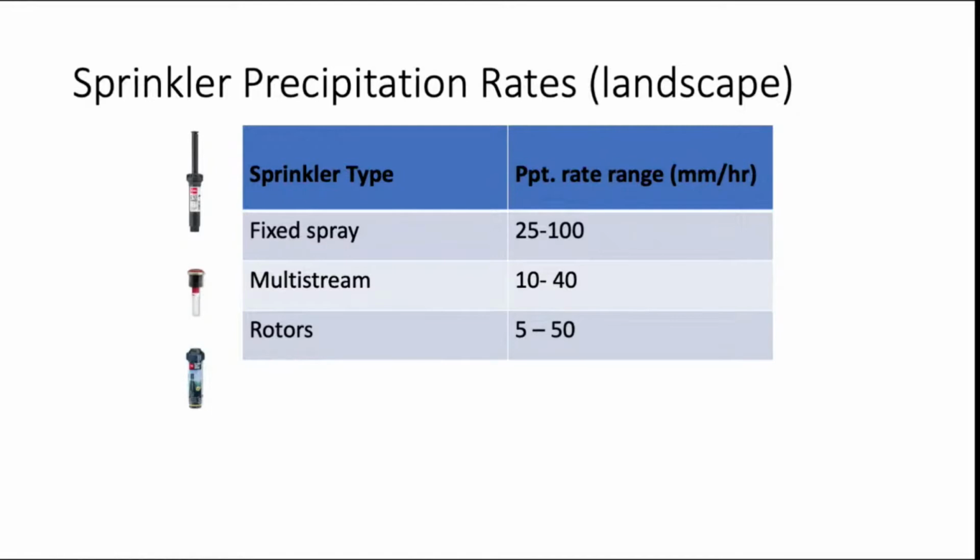And the soil infiltration rate usually starts high and then ends up at a basic rate, something like this over time. If we had rate on this over here, can't write very well with this mouse, but in time, ultimately it's going to get to what we call a basic infiltration rate to the right, where it levels out in that curve. And application rate should never exceed that, because it's not going to go in the ground, it's going to run off.